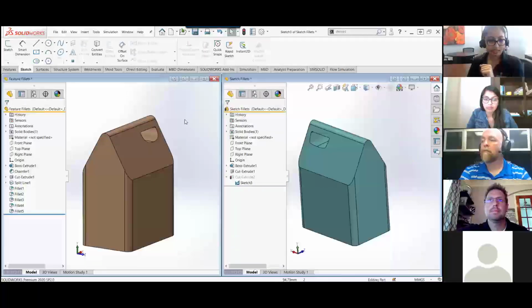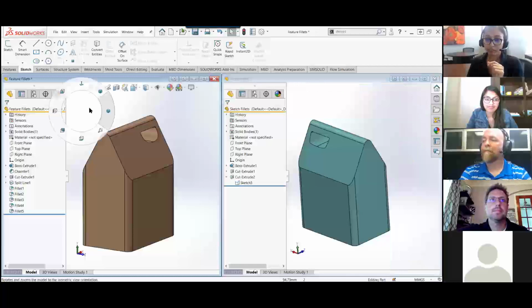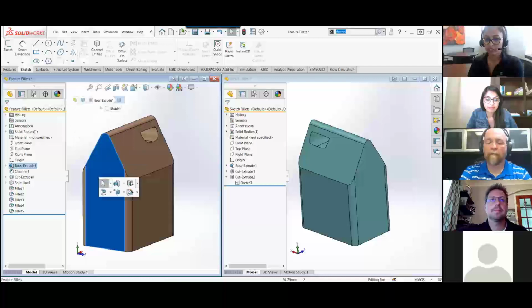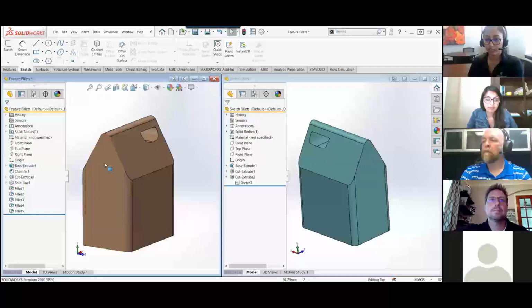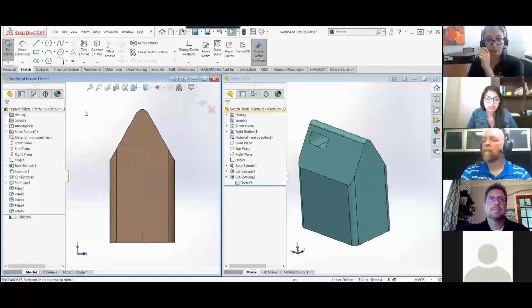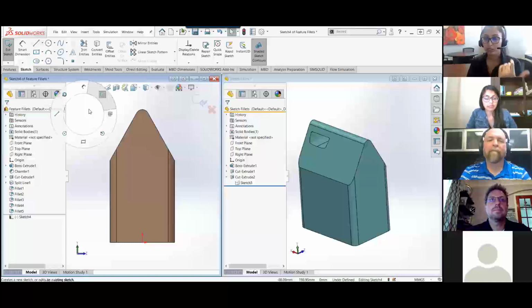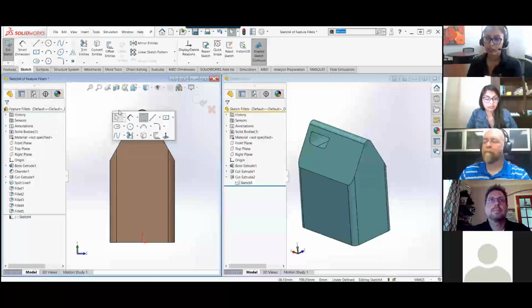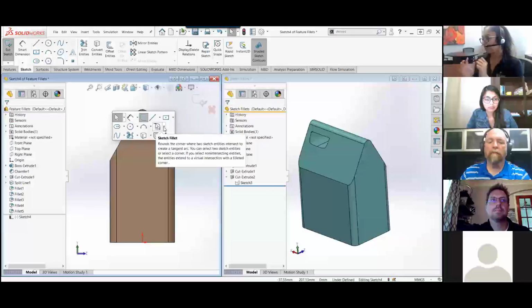Good stuff. Last little bit, a little bit of a Shivaniism. I like the mouse gestures Tim showed. On our parts and everything, we have different mouse gestures and different shortcuts. The S key is your shortcuts. I take advantage of the shortcut bar a lot with that S key, but I've mapped it to my mouse gestures. So whether I'm doing part editing or sketch editing or whatever, my shortcut bar is in the same direction. So I can access commands that I don't normally use very quickly without having to go up to the top left of the screen. That's my last little tip. With that, I'm going to pass it over to Stephen Darcy.